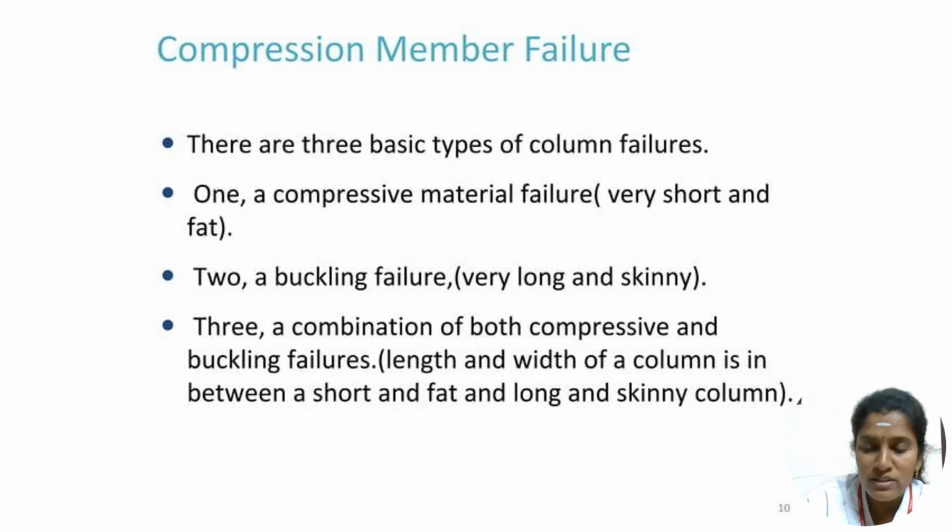What does the compressive material failure mean? It is a crushing failure. It will happen only in very short columns. If it is buckling failure, when will it happen? When the column is very long. So in that situation, this buckling failure will happen.